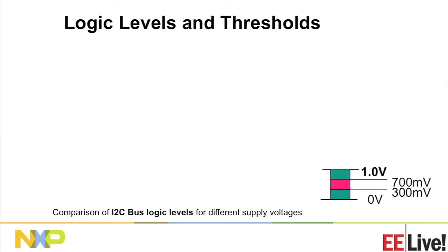What happens in the future? Future CPUs and similar devices that are in leading edge construction for semiconductor fabrication will probably run from 1-volt power supplies. They're very close now. Some of the Intel products that are in the marketplace are 1.25 volts. Some of them are indeed 1 volt or 1.05 volts. So to stay current with that technology, you need to take those 1-volt signals and step them up to something you can use, which is typically 3.3 volts.